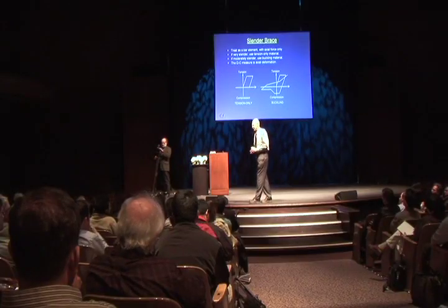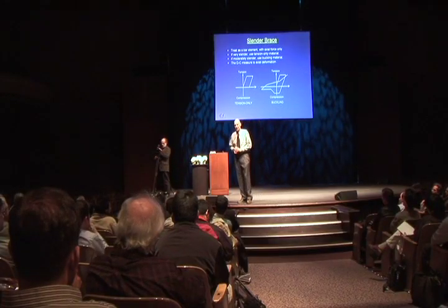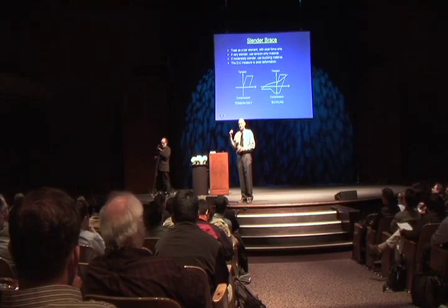But coming back to the original thing, you can model fracture. In the example I gave you with the pre-Northridge connection, the flanges were actually fracturing, and then the analysis was being considered taking that into account. If you really want to push the structure so that it actually collapses, I think you're asking the wrong question. I'm not sure that's an appropriate limit state.